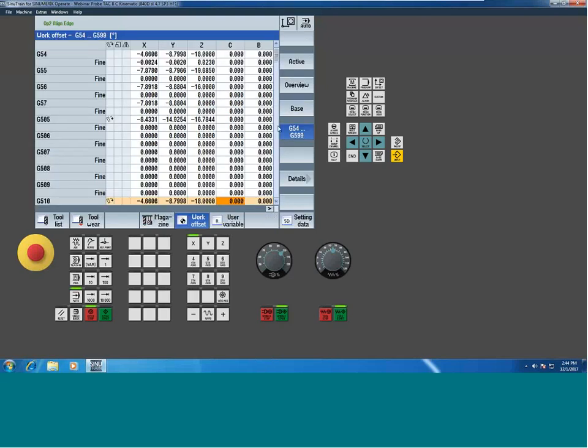So what did the system do here? Well, it knew that I was just taking a measurement of a rotary value offset, but it also automatically copied whatever values are sitting in the work coordinate system, and even the fine values for me. So it knows enough to say, hey, if you're going to do even something simple like an align edge, you're probably going to want those values down there. Now, you're probably going to update them at some point, which we do in a second here, but it copied them for me, even though I never measured anything in the X, Y, or Z.